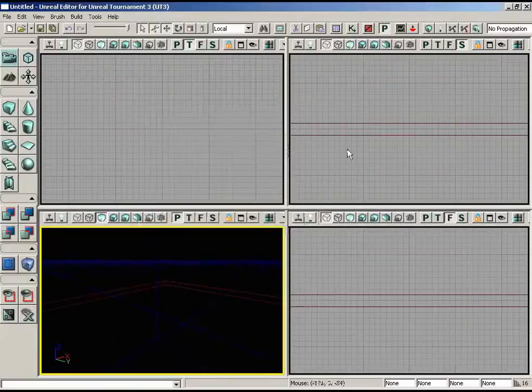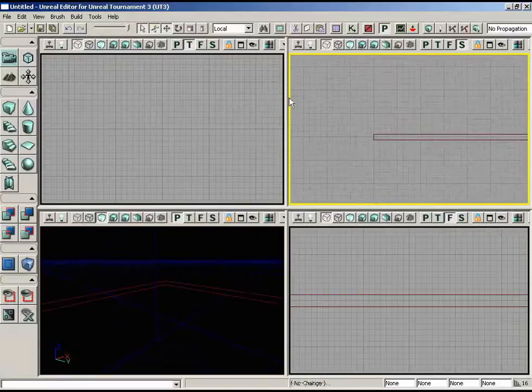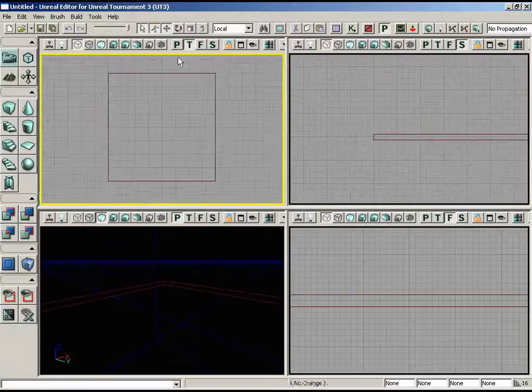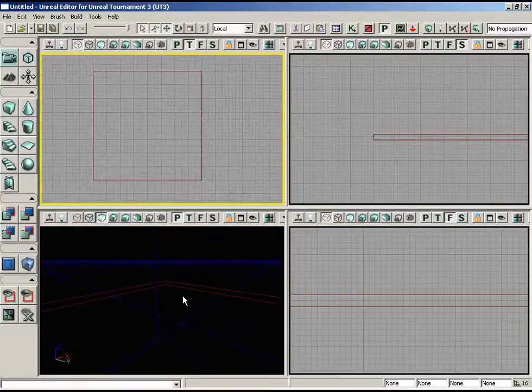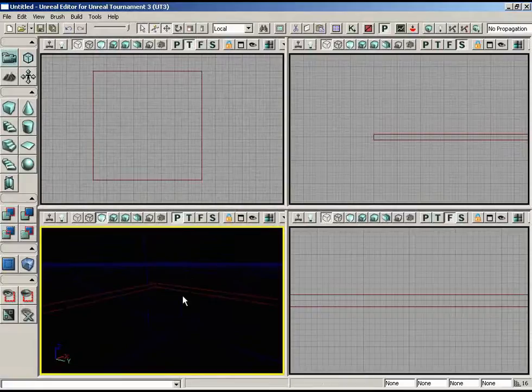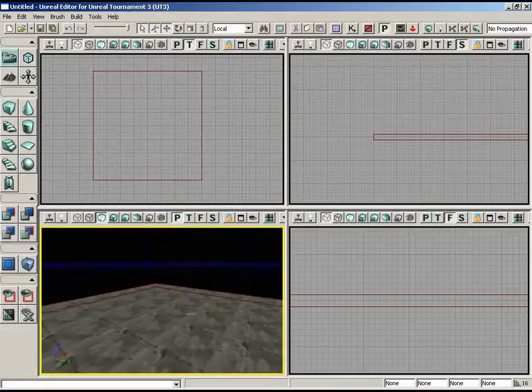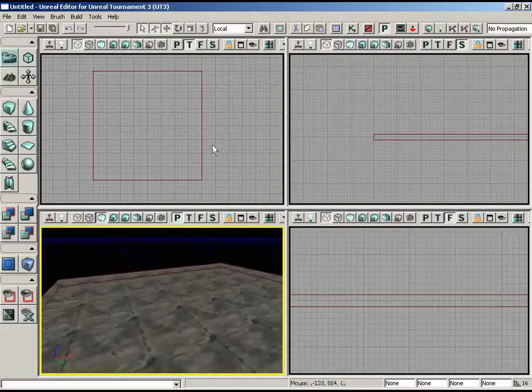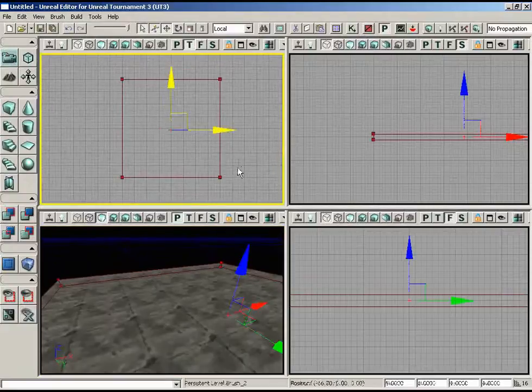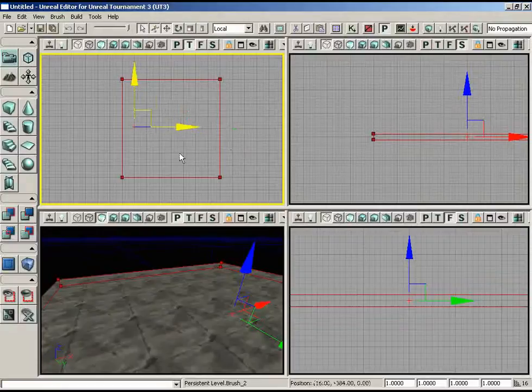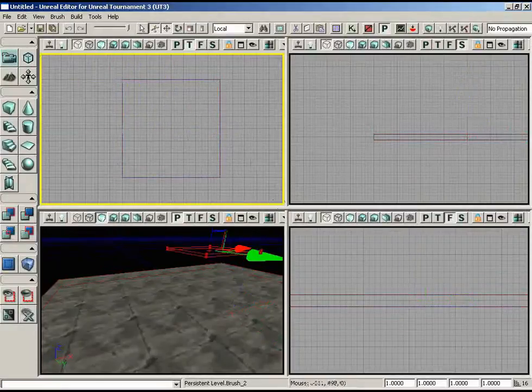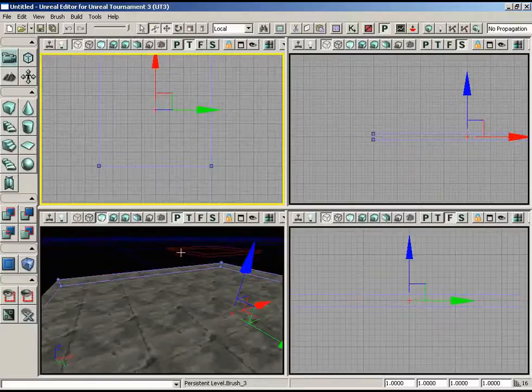We'll build that. I'll leave the brush aligned where it was in Z. If we scroll out, we can see that it's pretty much still centered on the world, which is fine. So with this brush now, we'll add this into the level. So I'll use the Control-A shortcut, and we have the floor base created. With that created, I can move the builder brush back out of the way. So let me just slide this back over, and I seem to have lock selection turned on, so we'll turn that off so we can move the builder brush back out of the way. So here's our additive brush.